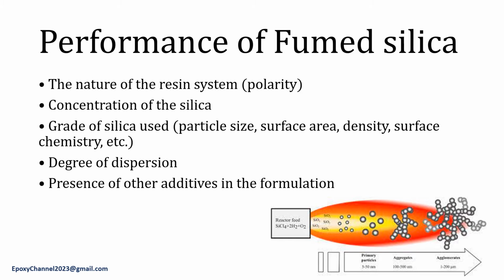High shear mixing equipment will improve the efficiency of fumed silica in the formulation. Often, silica should be added to the resin directly or to the more viscous part of the formulation with as little solvent or diluent as possible. Dispersing the silica in a concentrated base or master batching provides optimum efficiency and stability. Incorporating the silica before adding any fillers or pigments ensures homogeneous distribution.